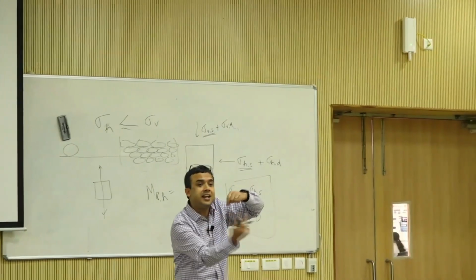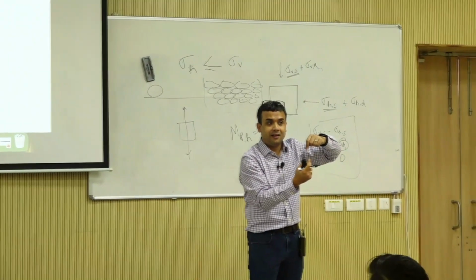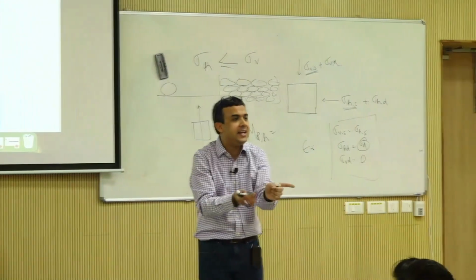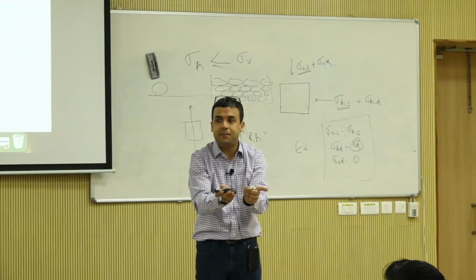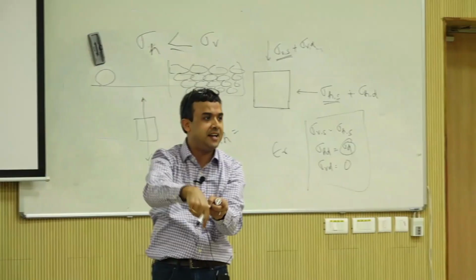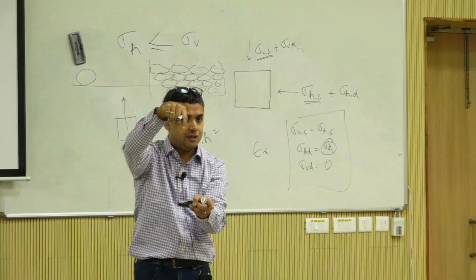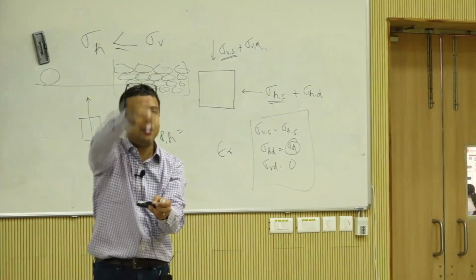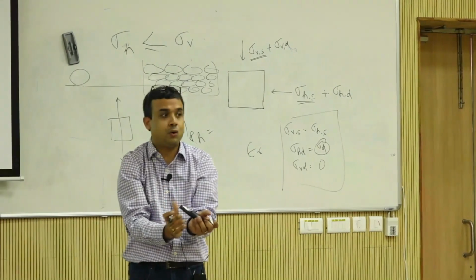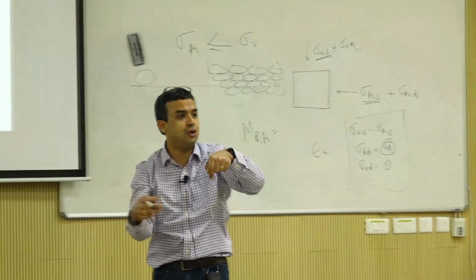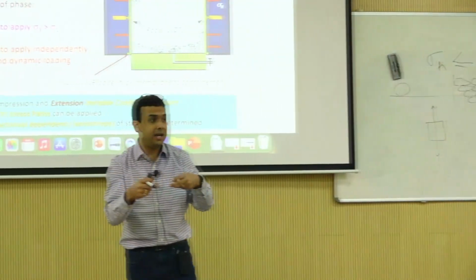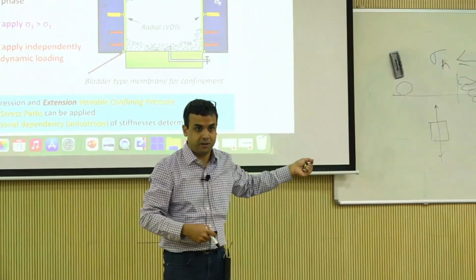It's still a cylindrical specimen, right? So the horizontal, the x and the y directions are probably similar, and they are different from the z direction, right? So there is one set of properties this way and another set this way. So it's called cross anisotropy. It's not truly anisotropic, it's not three-way, it's called cross anisotropy.